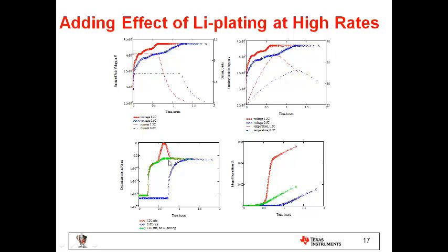Even though the area where it occurs is pretty narrow, when you integrate it and look at the overall degradation in charge, you can see that it results in a huge difference in the degradation in one cycle. It's more than double the degradation. Even though this is just a new battery effect, when the battery ages, the degradation slows down. But even for an aged battery, the effect is usually around 30%, which is a pretty high degradation effect.